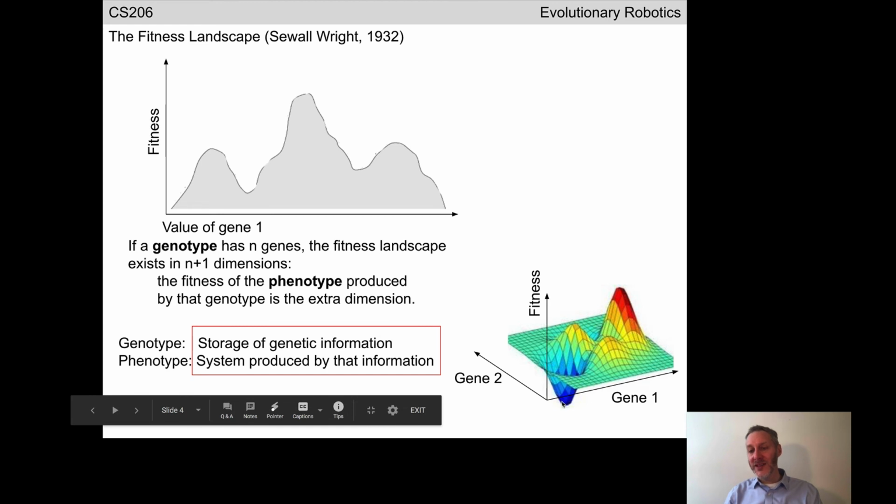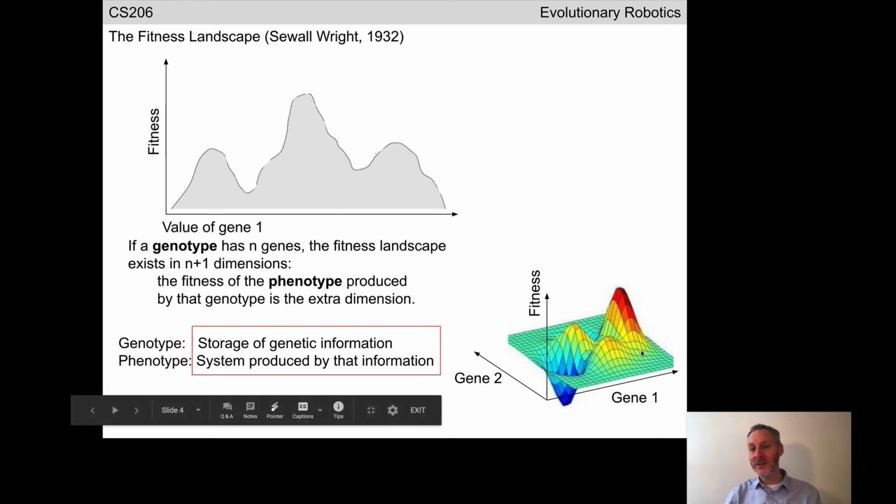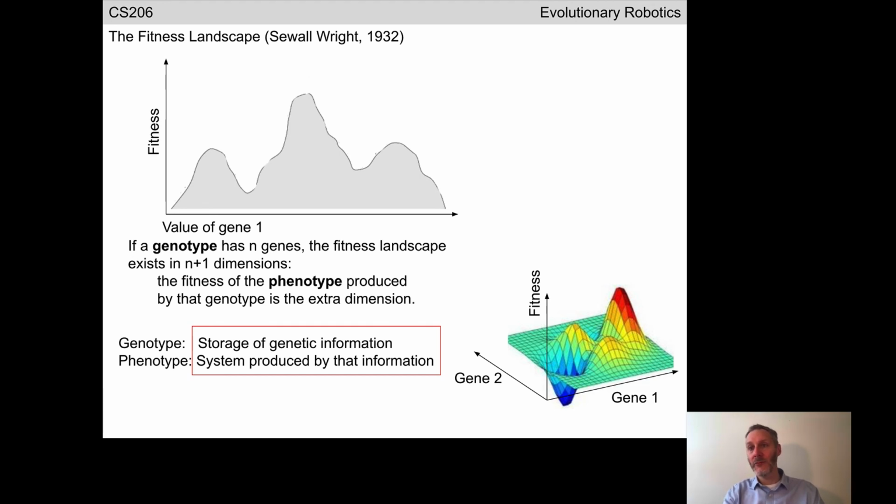If we take the same Braitenberg vehicle, the same two synapses, but we change the fitness function, we change what we want the robot to do, let's assume we change it to photophobia. We want the robot to run away from the light. What happens to the fitness landscape here? Let's imagine that this is the fitness landscape corresponding to phototaxis, turning and moving towards the light. What happens if we change the fitness function to photophobia?